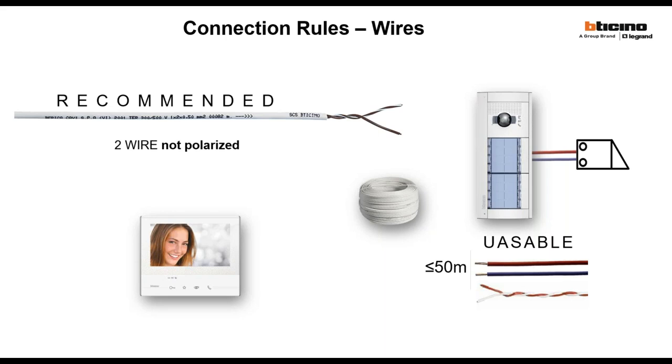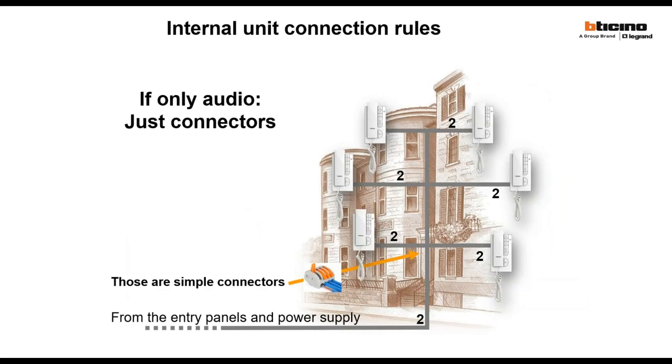If you use a data cable, you are in a middle way between the 2 kinds of cables. A data cable, I mean, using only 1 pair. It's important to use a pair because it's giving the balance to the signal.